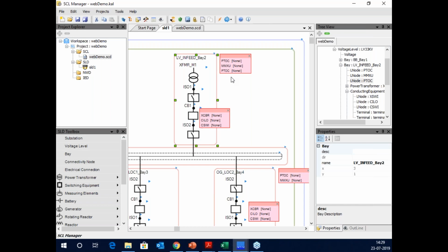So now I can cater to phase faults, phase-to-phase overcurrent faults and phase-to-ground faults. I can do that separately. So be more relevant out here at the outgoing feeder. So I could have multiple PTOCs.